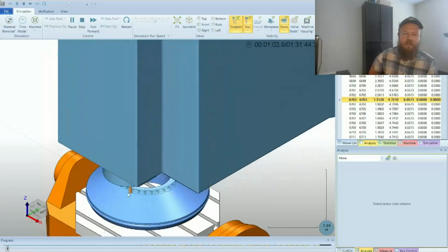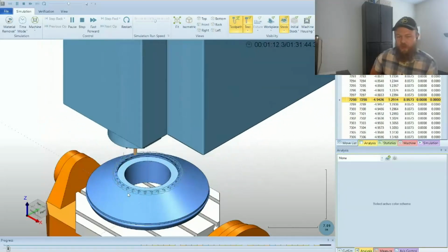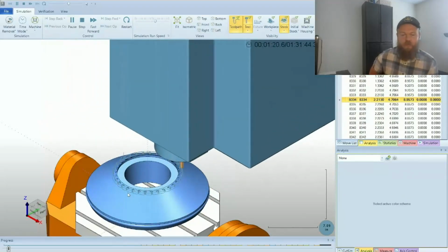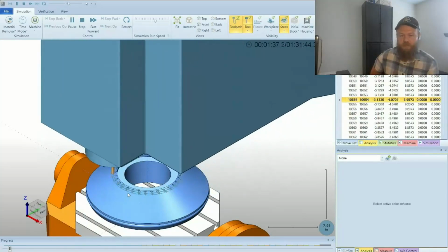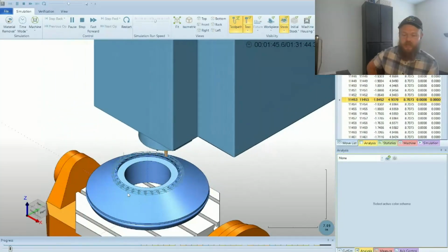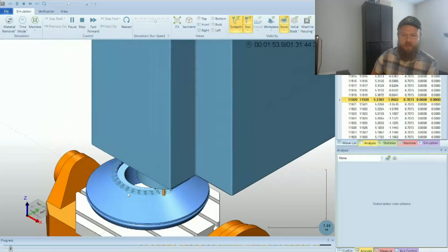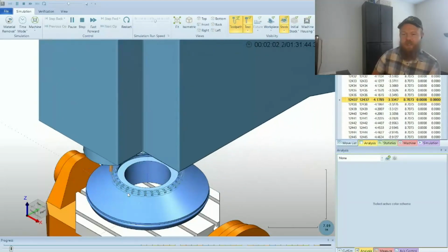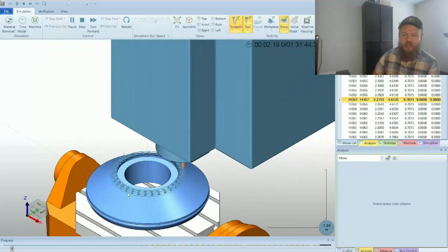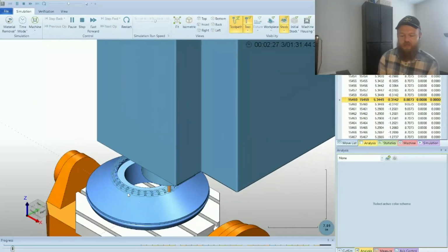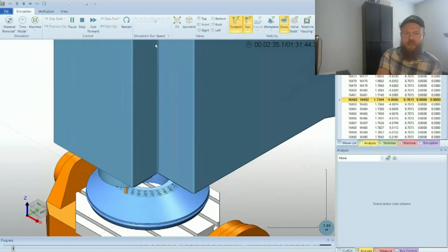Then we got into morph between two curves, which is one of the most frequent ones that I use in multi-axis machining to follow along any geometry, to have the toolpath be driven from the surfaces that you've selected in that operation. And then you have your swarf machining for a tool to follow along the sidewalls of the tooth of the gear here.